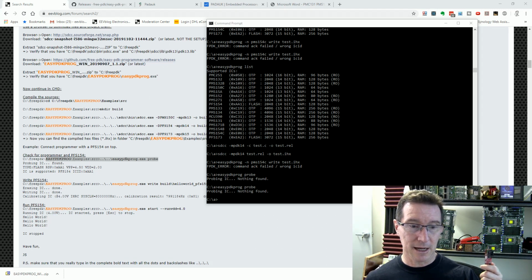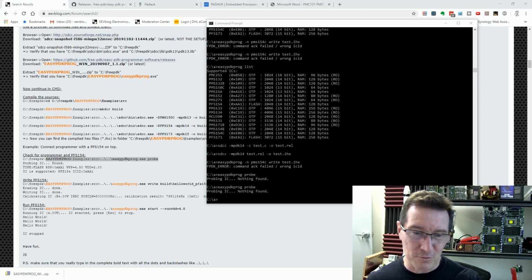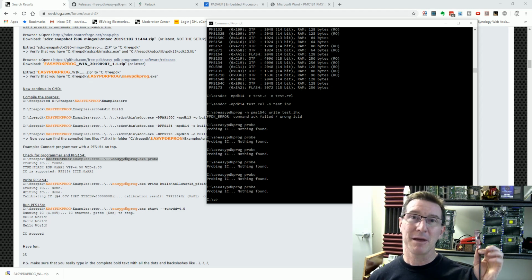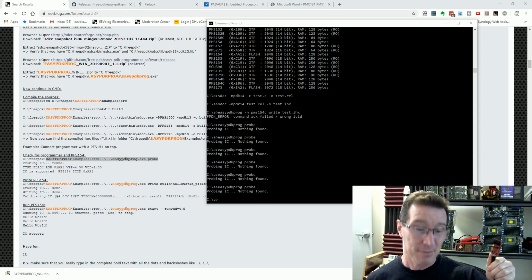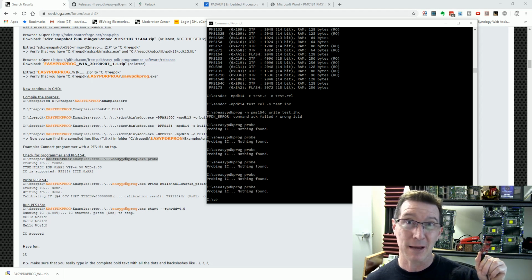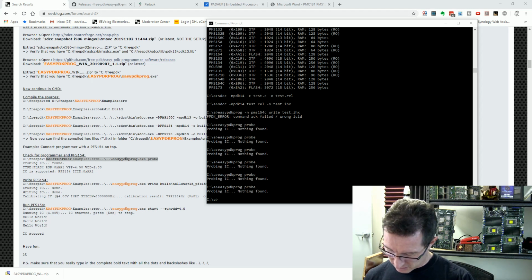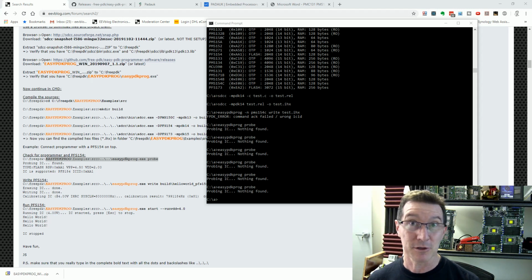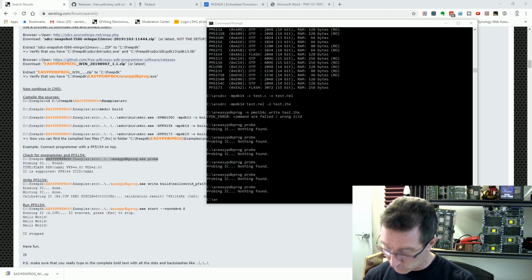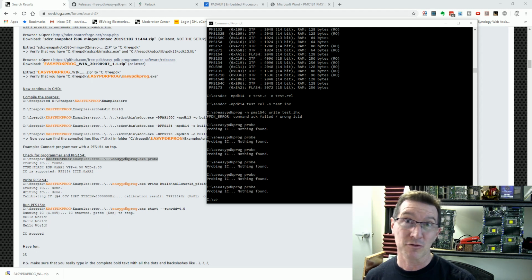I just tried the 131. I probed that and nothing found. So, yeah, hardware maybe. Okay, I tried to measure the VCC pin on the chip when I actually pressed program, and I had to put it in min-max mode, capture mode to capture that. It only captured 0.55 volts, so I don't know if it's simply too fast for the multimeter to capture or whether there's something wrong with the hardware.